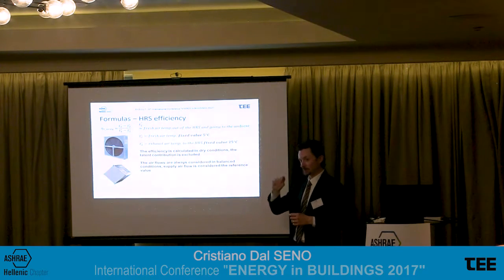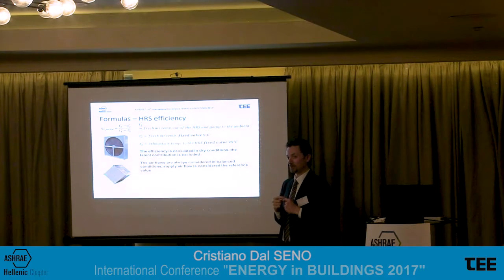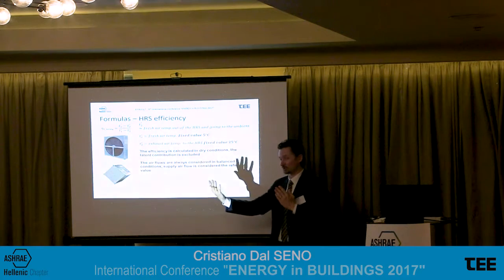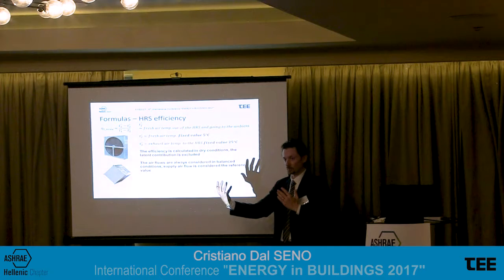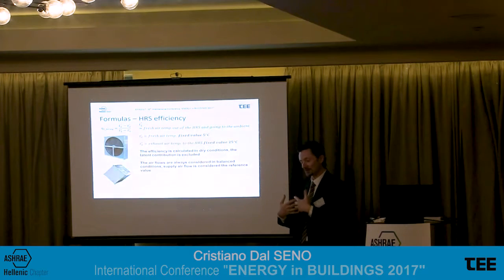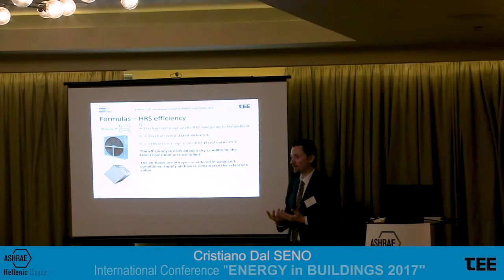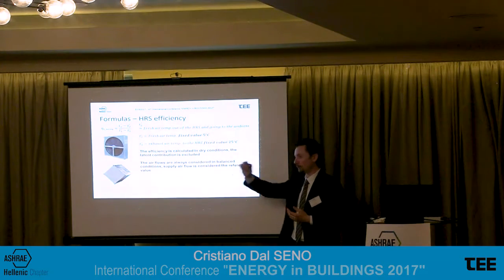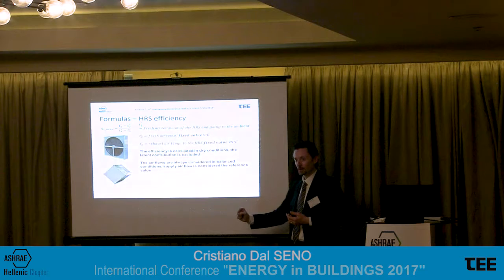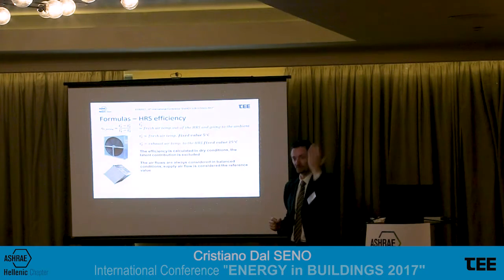I will see if it is complying with the 73%, and then I will recalculate it with the conditions given by the consultants. So you know that the plate heat exchanger is complying with the requirements of the norm, and then you will have an idea of the performances of this system at your conditions. So it is common to see nowadays technical data sheets where you see plate heat exchangers with 74% in one row, and then 3 rows just after in the line, 84, 84, 85.